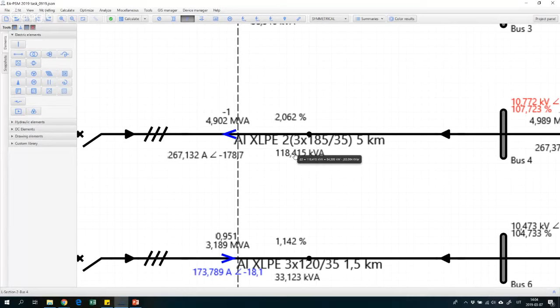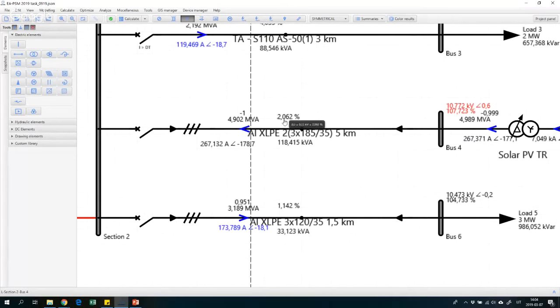So we have reduced losses by half actually, and also we reduced voltage losses by half, because at the beginning it was over 4%. So this is because I increased voltage in the network. The same power will be transmitted with a smaller current if I have a bigger voltage, and this will cause a smaller current and, of course, as a result, smaller losses.